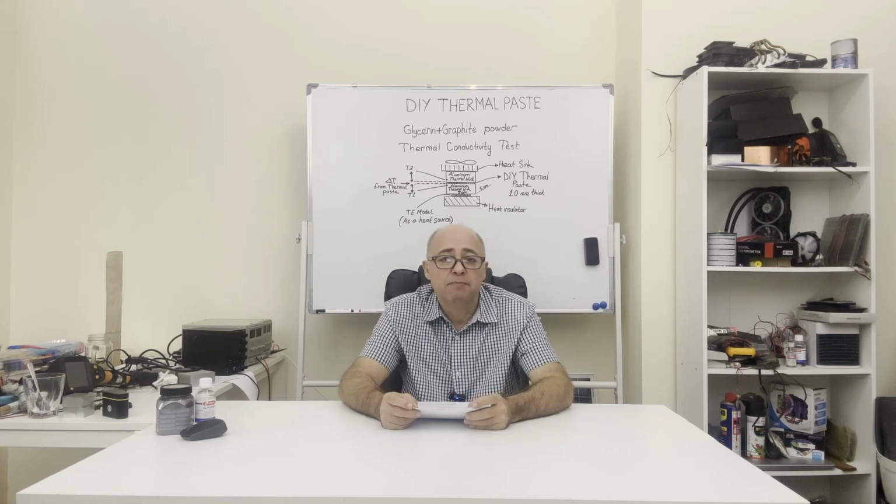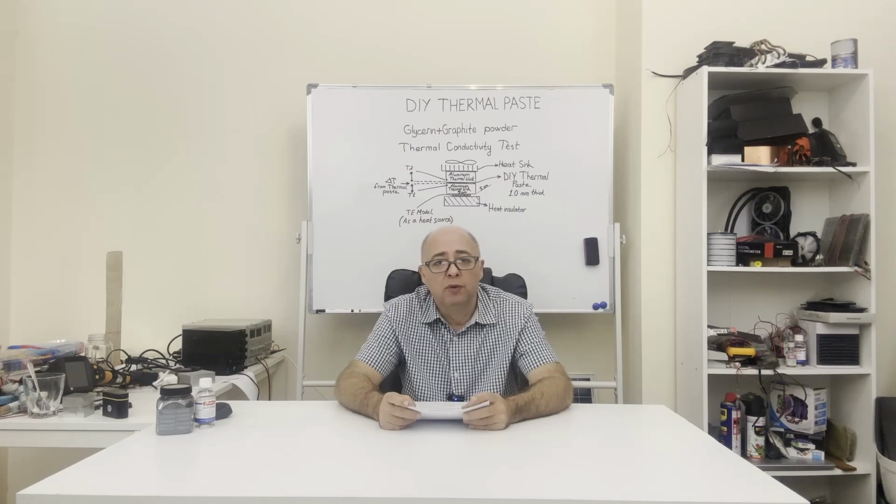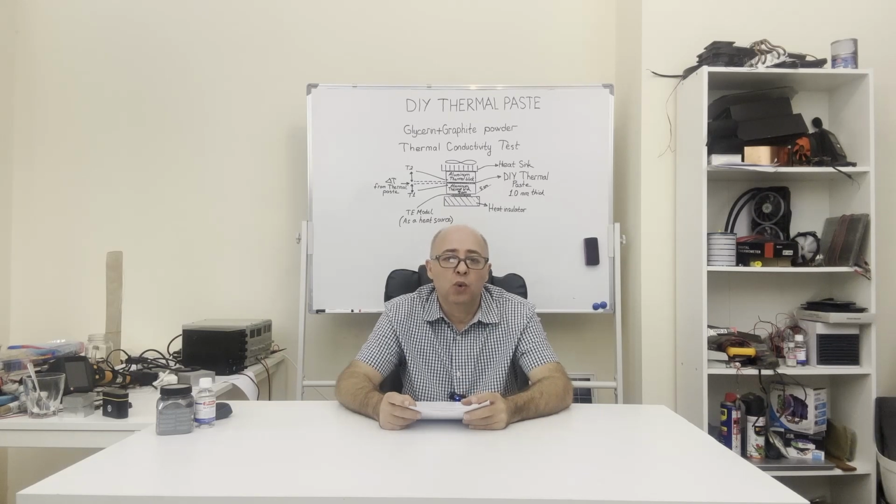The heat generated by the CPUs in our computers is removed by heat sinks, and the CPU is prevented from overheating. It's essential to use thermal interface material between the CPU and the heat sink contact surfaces. Desired features of thermal pastes: they should have high thermal conductivity, low electrical conductivity, be easy to apply and penetrate into gaps, not decrease thermal conductivity over time, and should not leak. After this summary information, let's come to our own project.